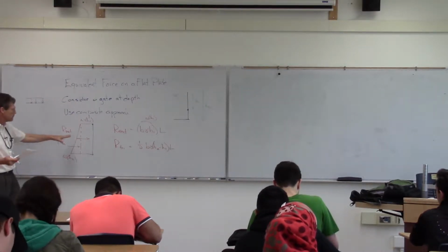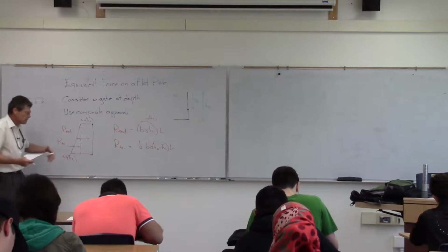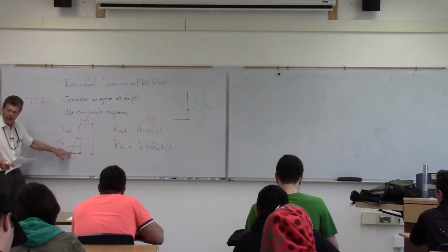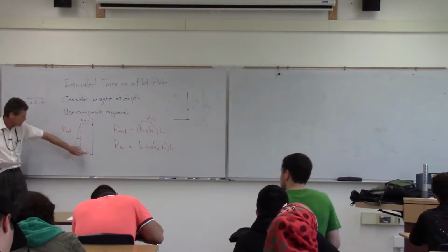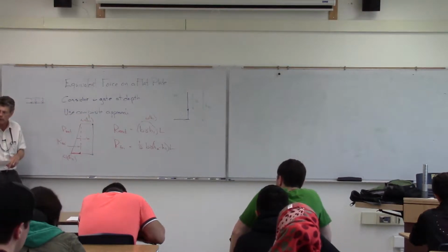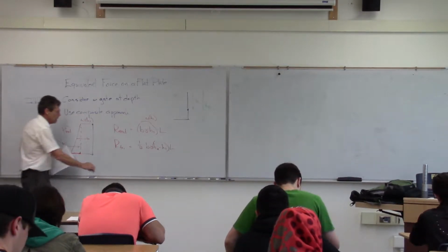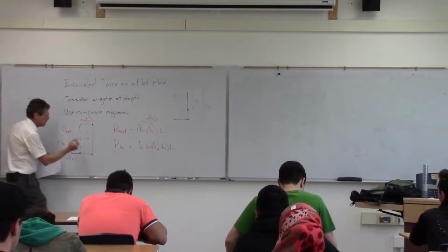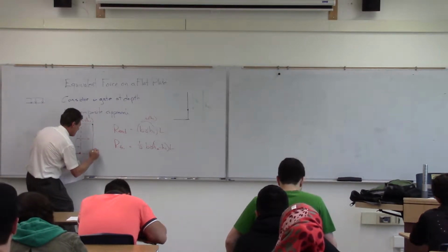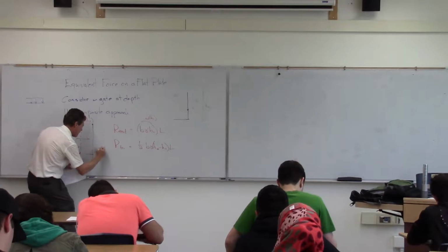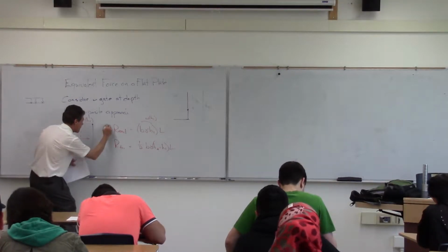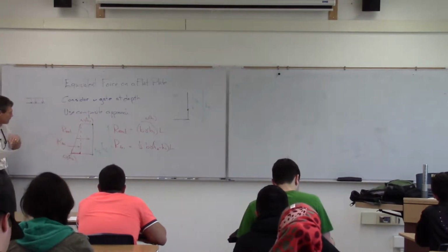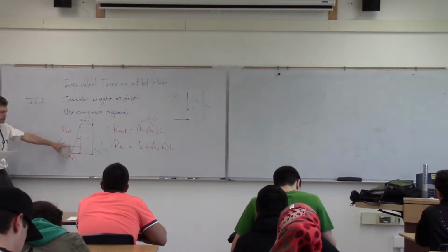And then the same thing with the triangle. Of course, it's half of that rectangular area there. The other thing to be very careful of is, remember, the triangle's this leg here. So it's going to be h1 minus h2. It's this portion of the leg because we've already accounted for this one in the rectangular portion there. And then finally, in terms of our moment equations, we're going to need lengths. Well, we know those lengths, basically. So rectangular, it's going to be halfway. For the triangular portion, it'll be 1/3 up from the base.